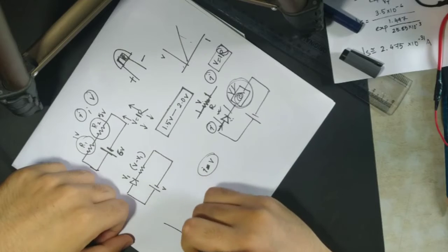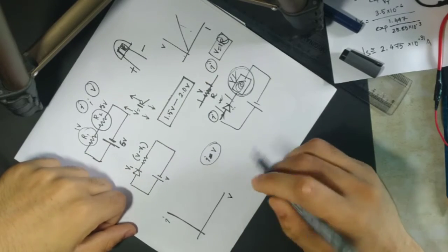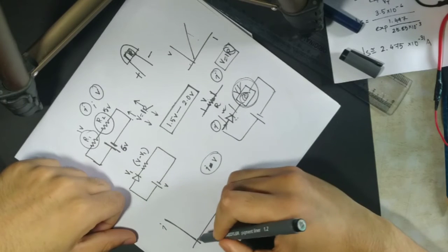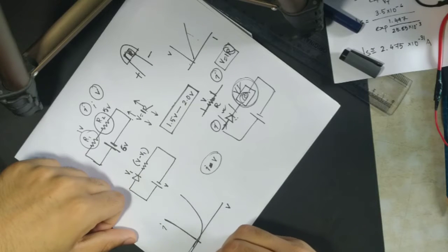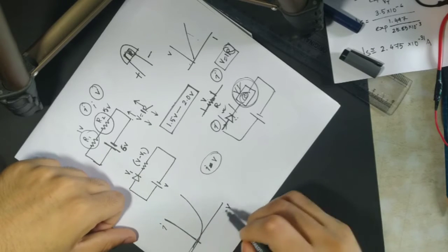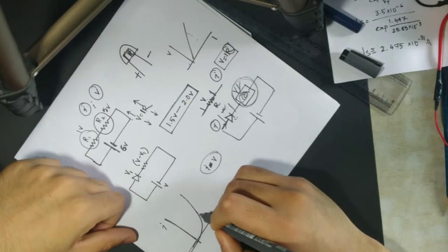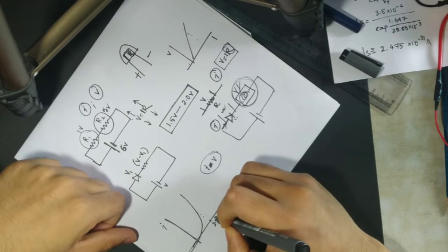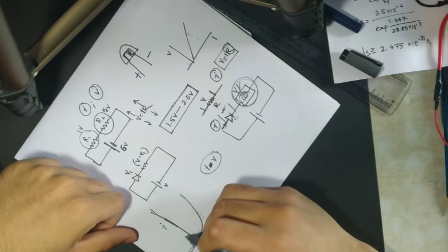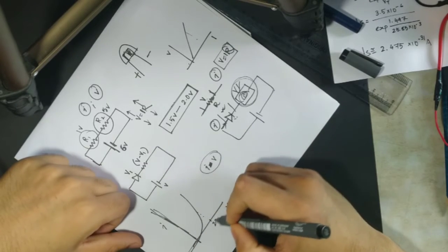Now if you plot a graph of I versus V for a diode or an LED, you see that the graph is somewhat like this, then there's also negative current, a very small current which goes through it. This is actually a graph of a diode, and at some point, say this point 2 volts, when you exceed 2 volts, the current through the diode will be immensely high and that will actually destroy the diode, so you should not go above 2 volts.